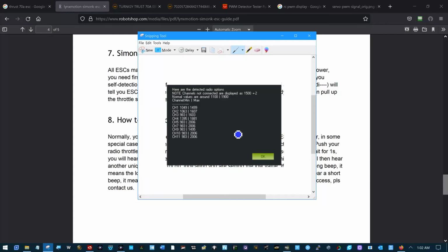If you plug your RC in and put it on your PWM monitor, and you see that that RC receiver is putting out a little different max and minimum pulse width than the one that's on the platform you're actually going to use, you're going to see those numbers are different by using that pulse width monitor and displaying the pulse width. And you're going to say, whoops, that receiver doesn't go all the way to 2005. I'm going to have to see if I can't find another one that goes to 2005. Oops, that RC receiver goes to 2100.